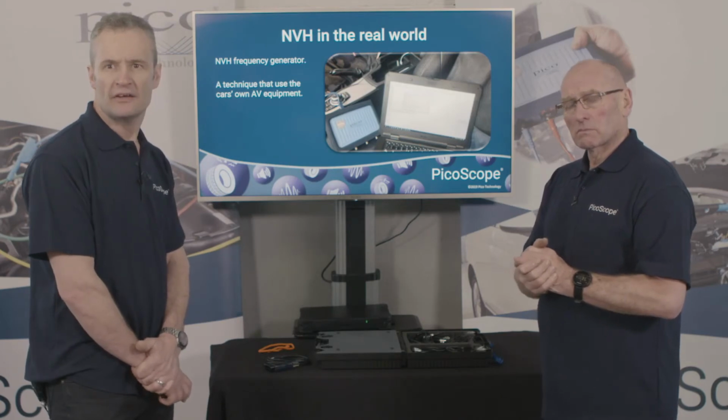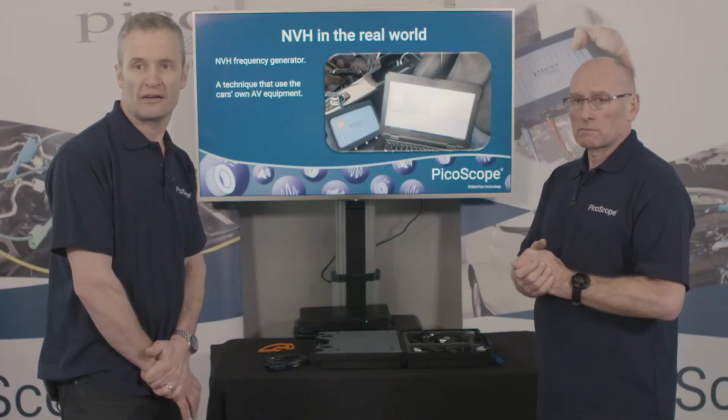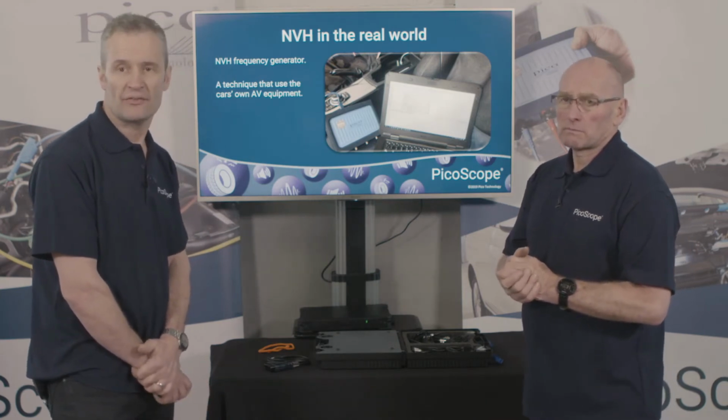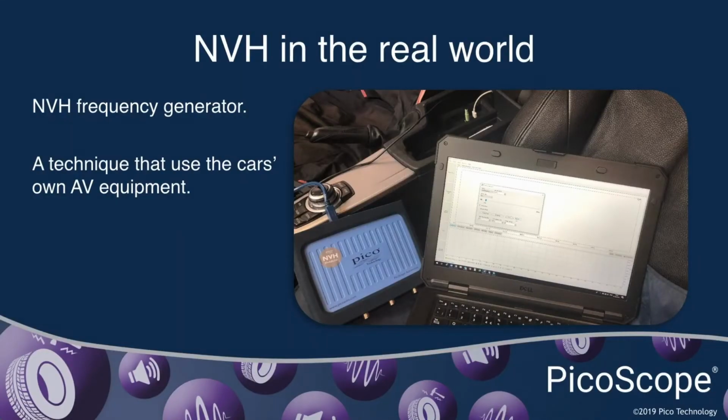If we were to set the radio audio volume to a specific level and then play various low frequency, booming, vibrating noises through the speakers, then maybe we can get the cabin to rattle without even taking the vehicle on the road. The ideal thing is we can do this with the customer present whilst they're in the car, so we can concentrate on the rattle they are complaining of. It's very easy to go out on road test and think you've identified the same rattle as they're complaining about, but in effect it's something completely different. Remember, we're all different as humans. So this feature will hopefully help speed up the time required to find these trim rattles and creaks.